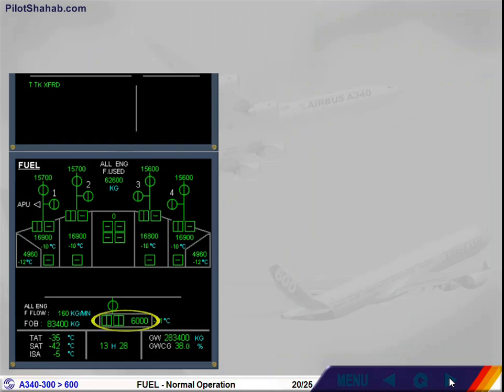The forward trim pumps run continuously as long as there is fuel in the trim tank. When trim tank is empty, the two trim tank pumps stop automatically. The trim tank isolation and inlet valves close. A trim tank transferred message appears on the engine warning display.